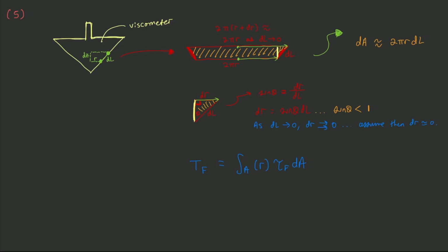So I would encourage you to stop for a minute and really think about what we just did. We started with this equation, and we know that we need a differential area to use this equation. So how do we determine a differential area on this conical viscometer? Well, you draw a differential area. We decided to draw a differential area with a differential z, and then we unraveled that differential z by cutting this segment out of the conical viscometer and unwrapping it and coming up with this skew shape right here.